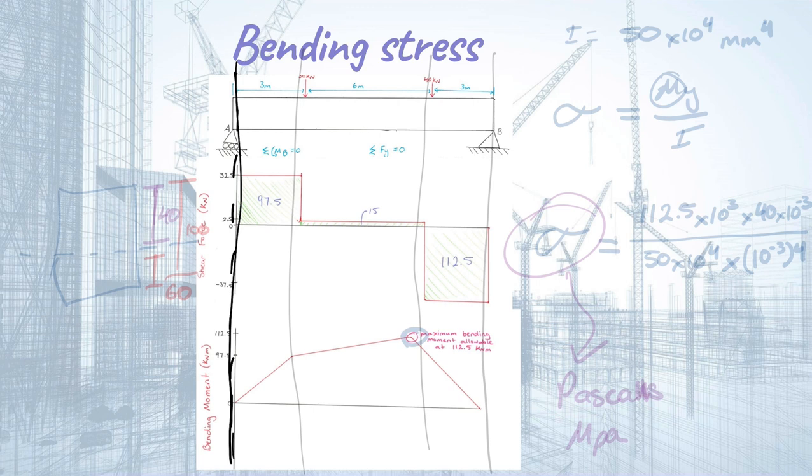And as you can see, overall, both graphs are going to line up with your original loaded beam. So you should have these points lining up roughly with the loads applied in that first loaded beam diagram. And that's an easy way to draw it in an exam. Just take a ruler, you can draw through the question and line it up in that way.